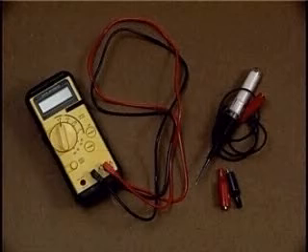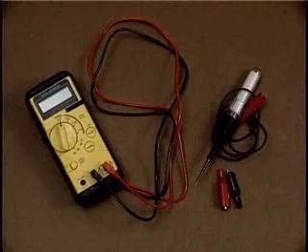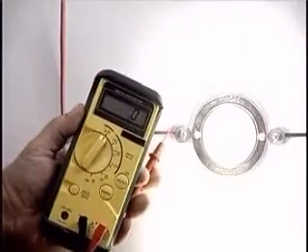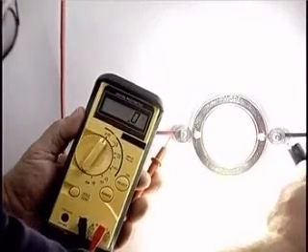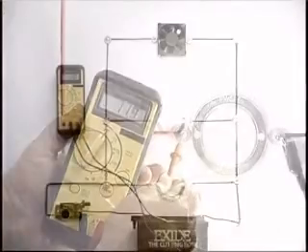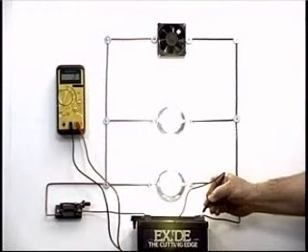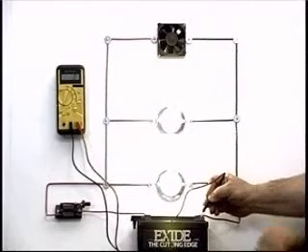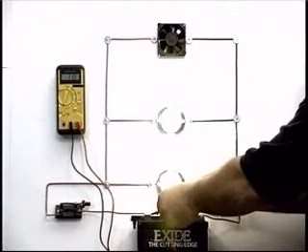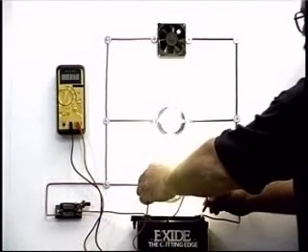Now that we have introduced and defined each of the terms used in understanding electricity, we'll use some basic test equipment to confirm circuit behavior and performance. A voltmeter is used to measure the voltage between 2 points in the circuit and is connected in parallel to portions of an active circuit. The black negative connector is attached to the end of the circuit connected to the negative battery terminal. This is usually referred to as ground. The red positive connector or probe is touched to the conductor at points where the conductor is exposed, such as connectors and terminals.